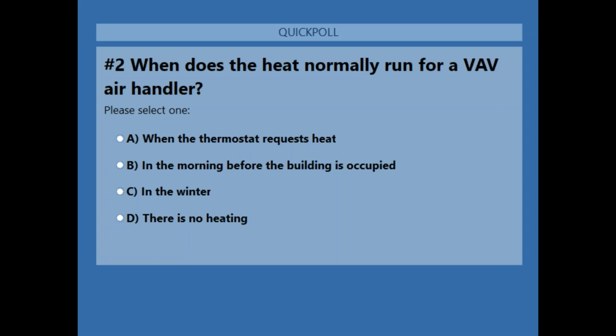However, as you saw in my previous drawing, I had one thermostat on 2 dampers for the interior zone, and that's allowable and sometimes does occur, and that's maybe because it was easier from a ducting standpoint. And maybe it was easier depending on the size of the dampers. Maybe putting 2 small dampers in from a ceiling height perspective was easier than one giant damper.